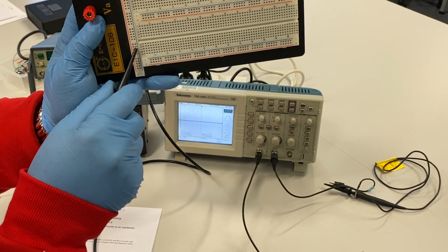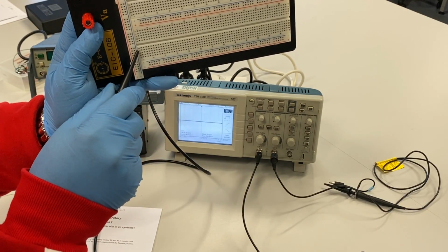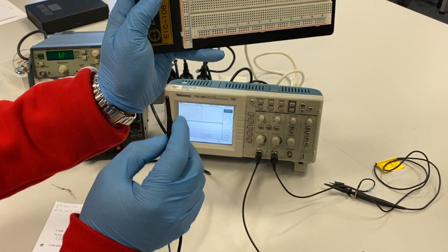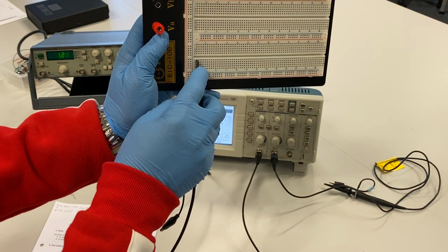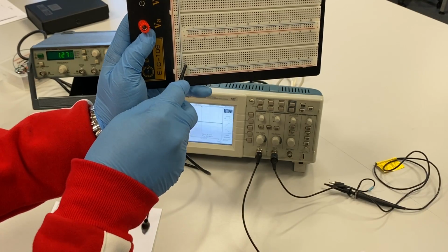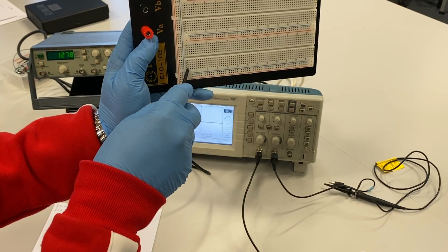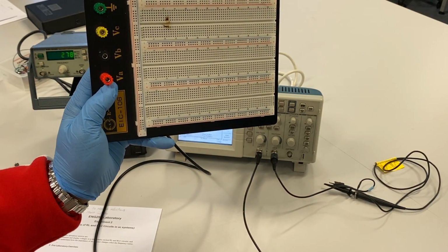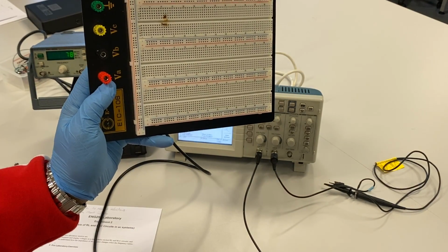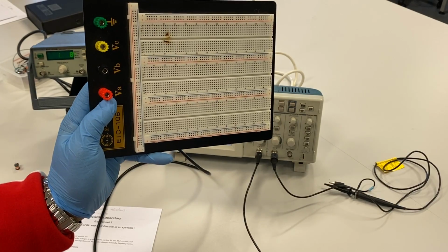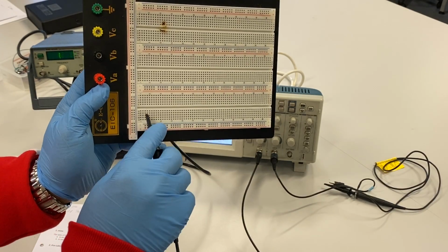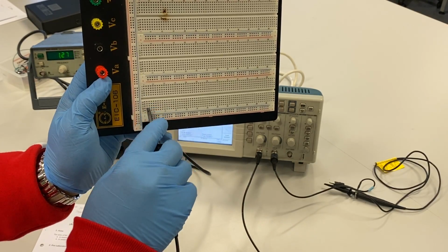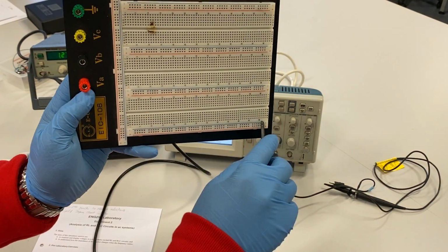Now, if we go into the mid section of the breadboard, this mid section has got 1, 2, 3, and A, B, C, D, up to E. So it goes 5 points. These 5 points, if I'm holding it like this, are connected vertically. It means if I put any voltage value here, that whole line A to E is now a node that has exactly the same voltage. That is, if I look vertically at the midsection of the breadboard.